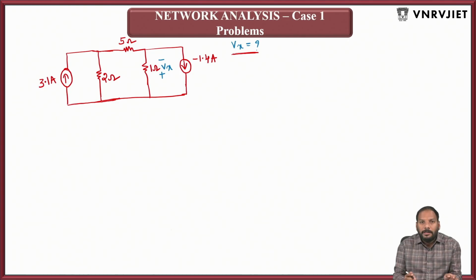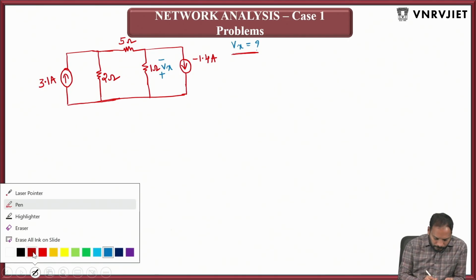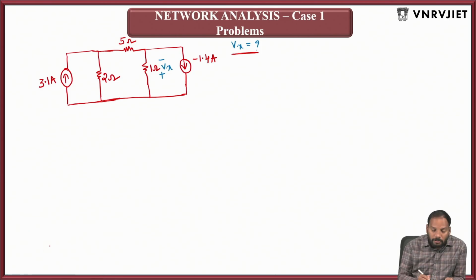Going ahead to solve this, I said you already, try to redraw the circuit by removing the unknown things. Actually here the unknown thing, or the question requirement, is the value of Vx, right? So we'll try to eliminate that Vx and redraw the circuit as follows.